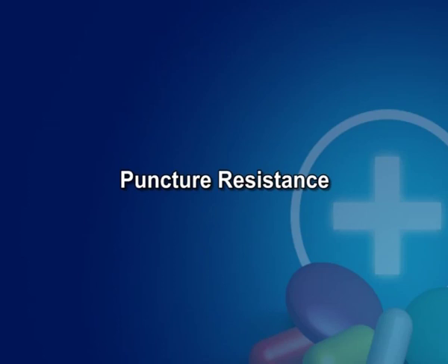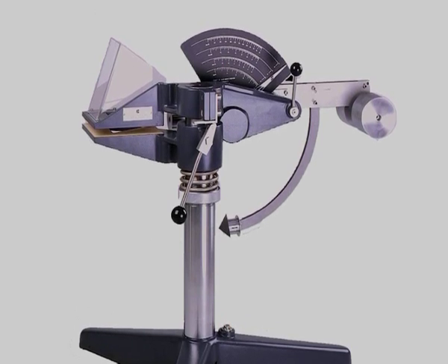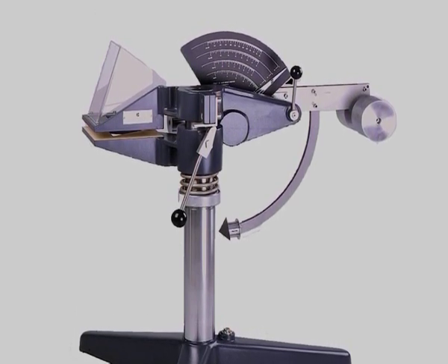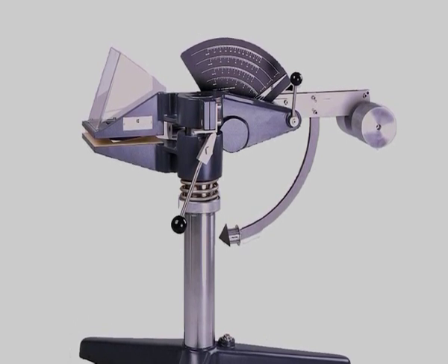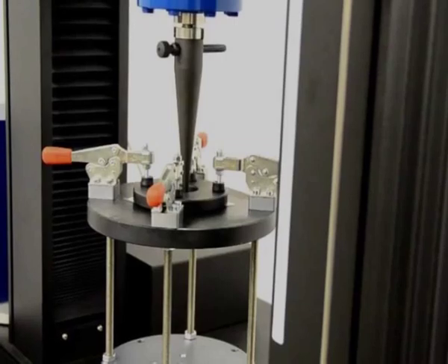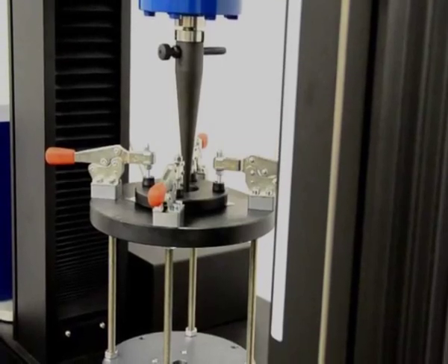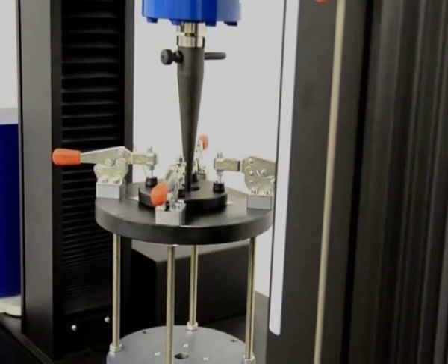Number 12 is the puncture resistance. A triangular pyramid puncture head is attached to a pendulum. It is released to swing onto a test piece. The energy required to force the puncture head right through the piece, that is, to make the initial puncture and to tear and bend open the test piece, is measured.